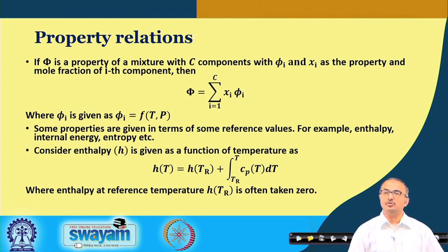So, whenever you are looking into literature and you find enthalpy values, you will also see that the enthalpy values are related to some reference values, and be very careful in this, since different literature may have different reference values at different reference temperatures.